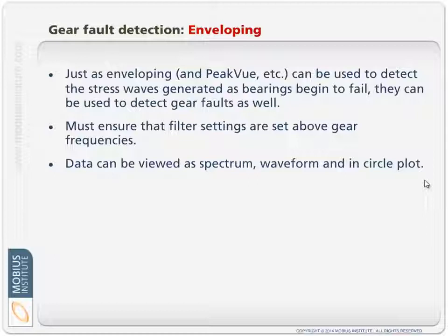In the normal spectrum it's kind of being swamped out because there are all other higher sources of vibration. It's a very short event. It may not be picked up very well in the FFT. There's a lot of issues there. But because we see that as a spike which causes excitation in the higher frequencies, we're exciting higher frequency natural frequencies in the structure or in the sensor itself.